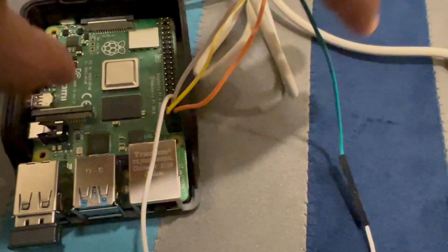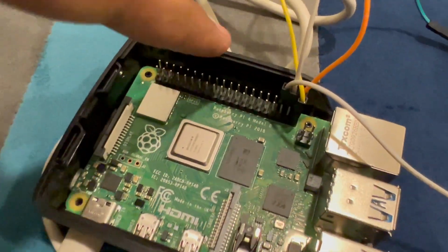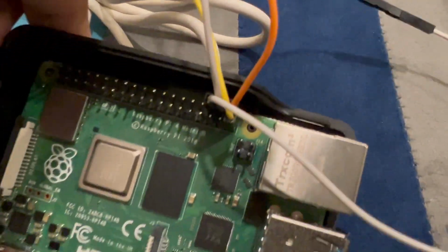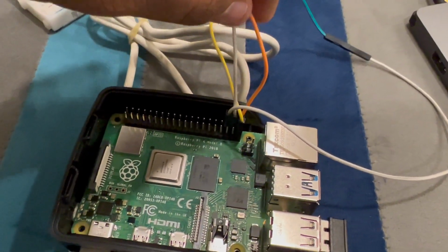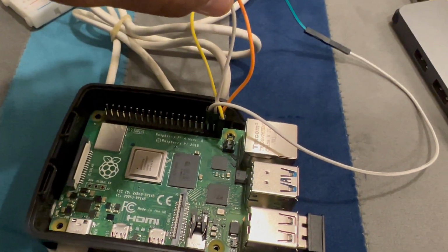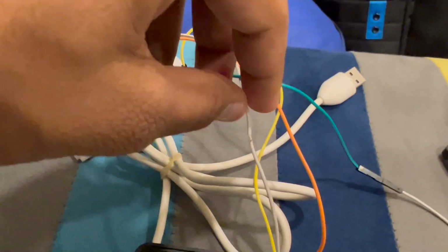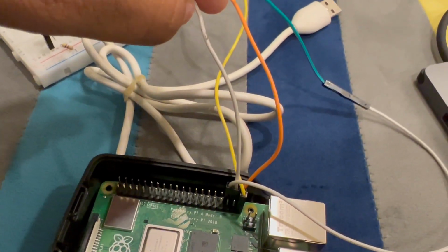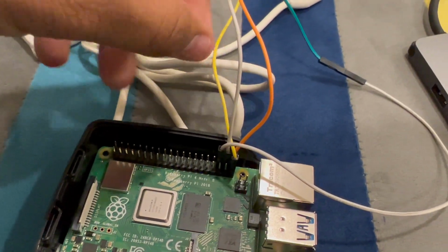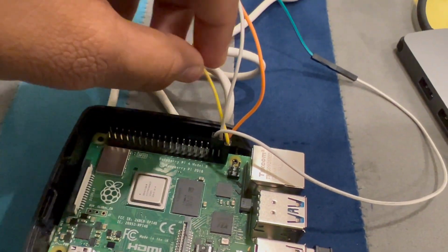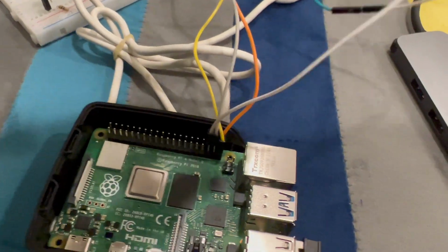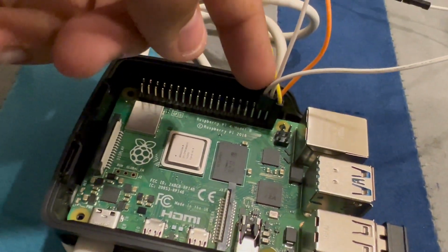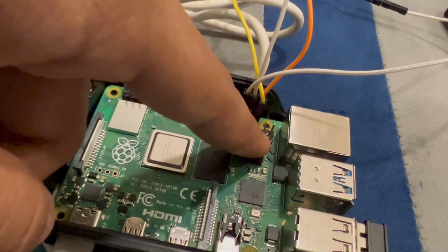These are consecutively placed at the last 3 lines, like this is the 39th pin, the yellow wire, which is for the ground, and here you can see the orange wire is for GPIO pin 21, and the white wire is for the 38th pin, which is GPIO pin 20, and for GPIO pin 16 this is the cable which is number 36. So these GPIO pins are consecutively in 3 lines, these 3, and this is the ground.